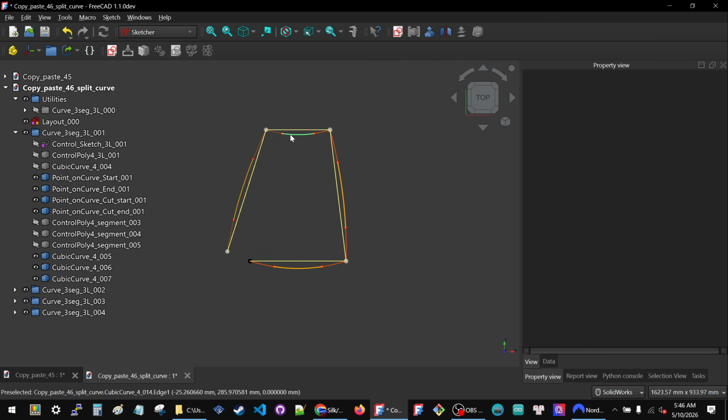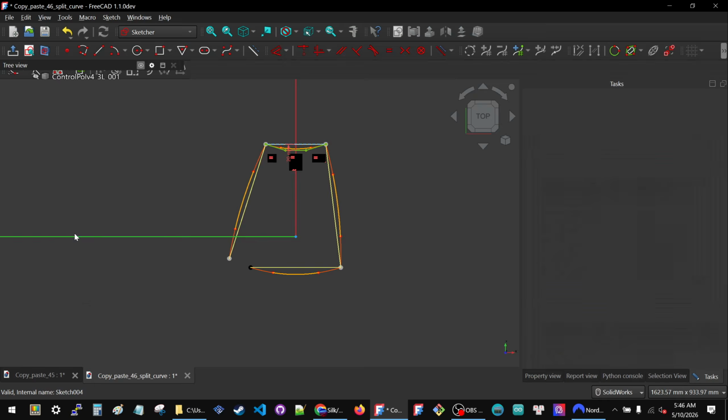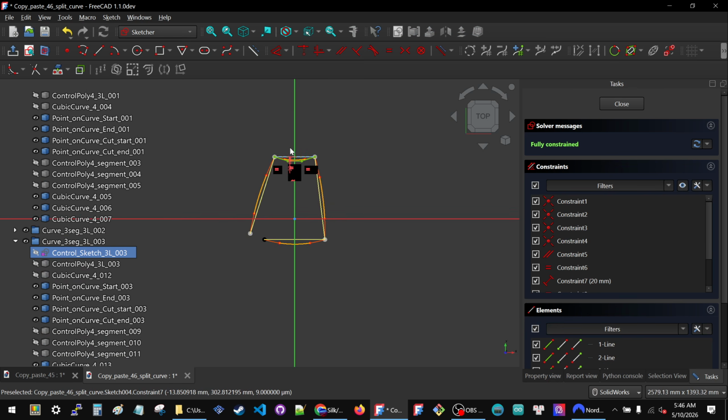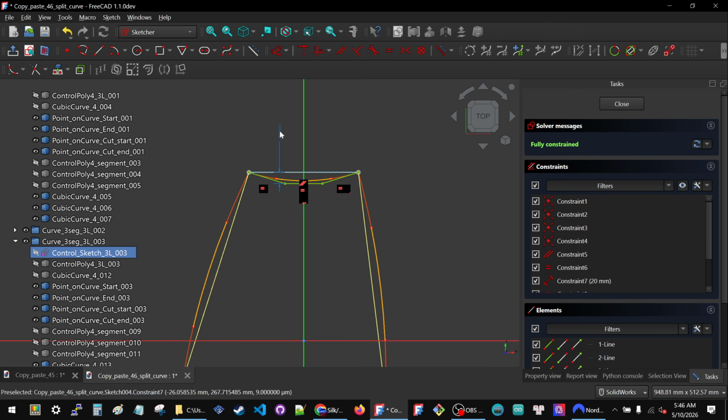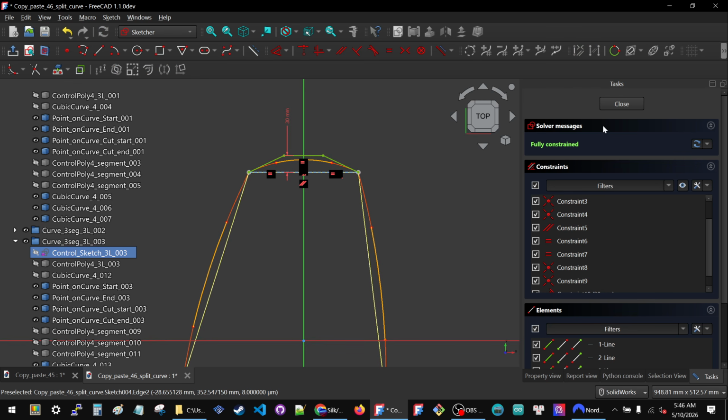So then I'm going to fix this one. It opened the folder for me. I go back up to the top. I find the dimension. I wish I could flip it, but FreeCAD won't let me, so I just drag this, select the point, select the edge, type D. Oh, it did not select the edge, so I'm going to select it now. Make this one 30 also.